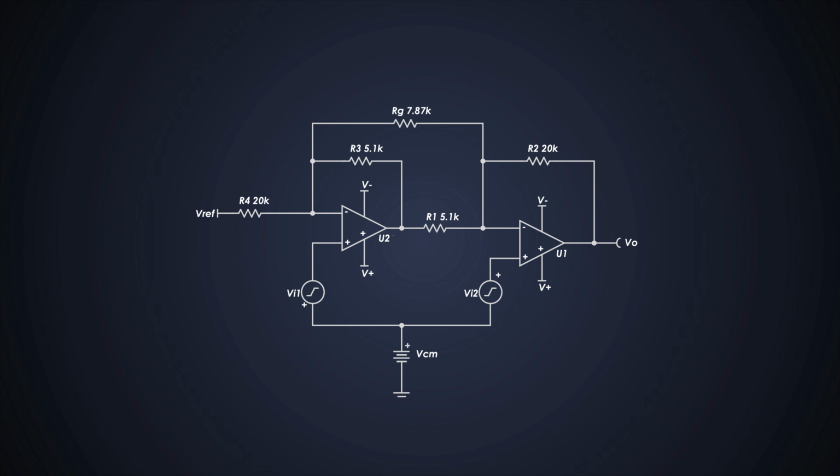This circuit has the obvious advantage of having only 2 rather than 3 op-amps, and it provides savings in cost and power consumption. However, the non-symmetrical topology of the 2 op-amp instrumentation amplifier circuit can lead to several disadvantages, mostly in lower AC CMRR compared to the 3 op-amp instrumentation amplifier design. The input resistance is high and balanced, so it is acceptable if the signal source has unbalanced output impedance.